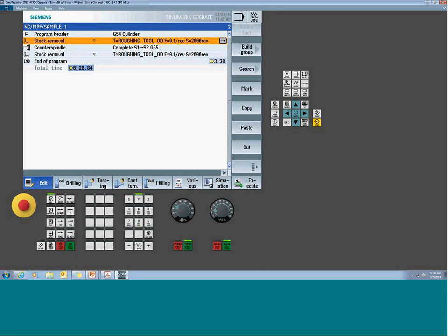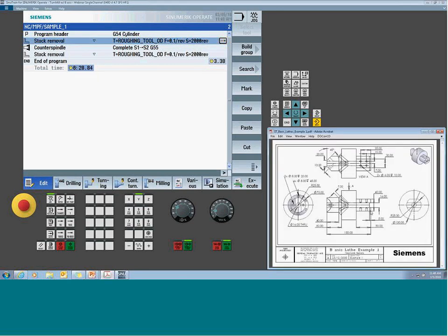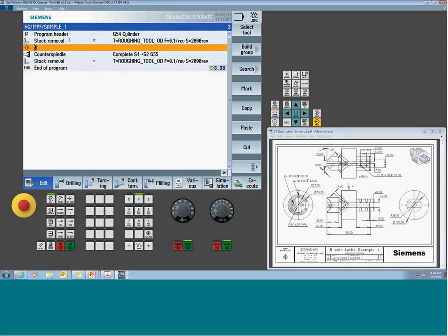I'm going to add that to my first op, because if we look at our part print, the slot is actually on the right side. What I'm going to do as well, to keep from doing the transfer, because we're going to add a few operations to this main side and let the other stuff get pushed down, is put a quick little G-code line in of a stop. This way, I don't have to worry about simulating the entire process the whole time. We can work on the part, get done, and go over to finish off the back section of it.